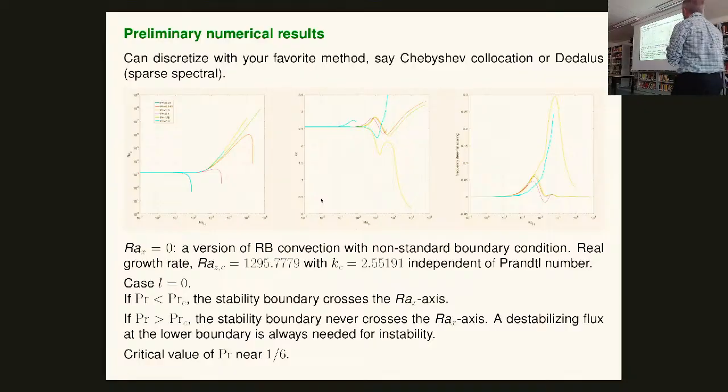But you start off with simple things. So this was saying, okay, let's understand what happens if I take 2D disturbances with no wave number in the L direction, the Y direction going into the board. And these are our first calculations. So you take a horizontal Rayleigh number and a vertical Rayleigh number, which is, I'm afraid, flipped around from what we did before, but never mind.